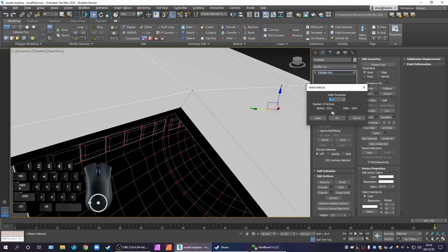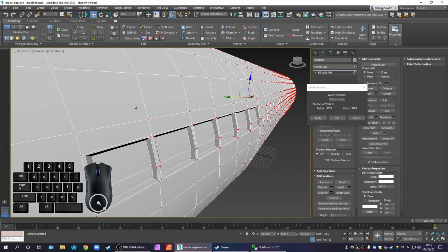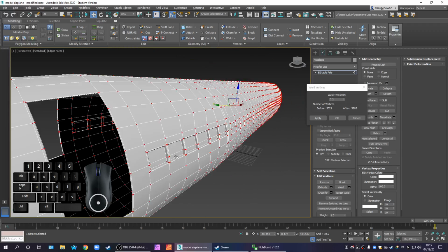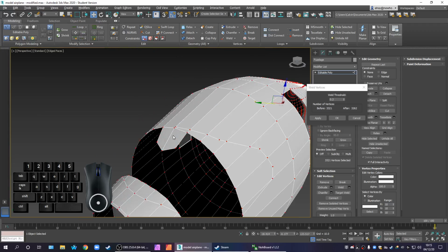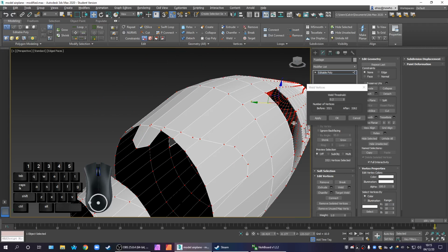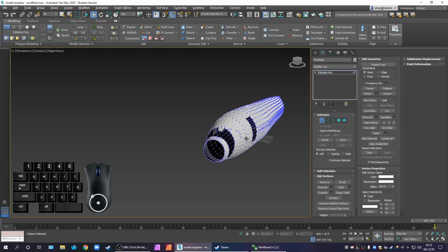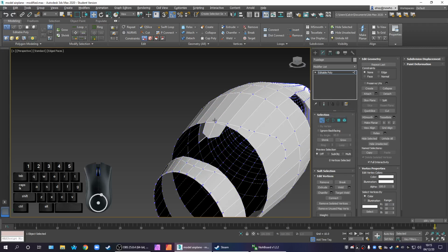But here I am cleaning up over 100 welds, right? Well, almost 100. 0.2. 0.2 is even better. And I don't see anything wrong anywhere else. So I know it's just all vertices that are right on top of each other that I didn't want from that symmetry. So I'm going to hit OK. And now our situation should be a little nicer.